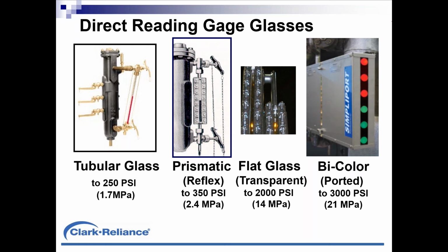With a transparent gauge, these applications display water as clear, steam as clear. So if you lose sight of the line, you don't know if the level would be in the blind spot or full or empty. What you're looking at here is the gauge being backlit with a modern LED light, and it presents a star-like image in the window sections where the meniscus line is. How that works well is the lights are actually aimed uphill from the back side, so it illuminates that meniscus to look like a lighted bubble.